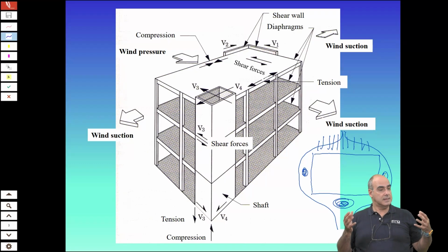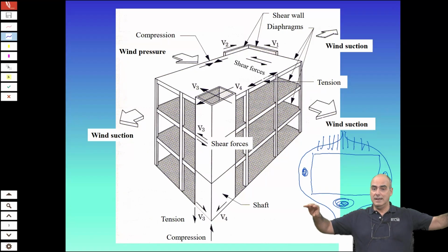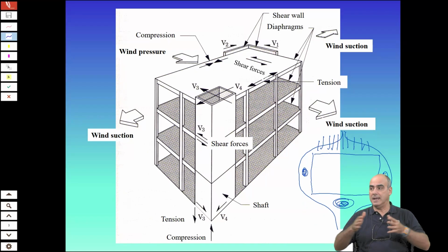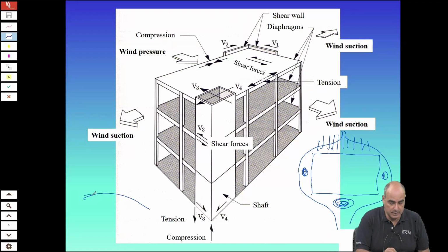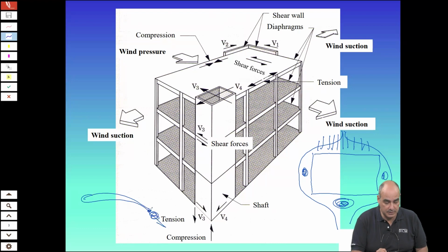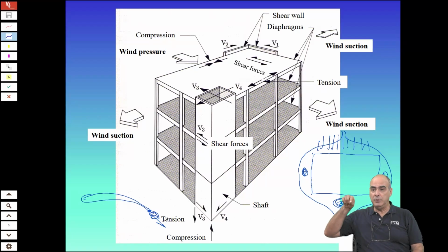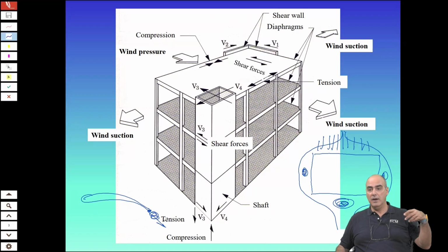Well, the same thing happens in airplanes. You have a wing. At the tip of the wing, you create a turbulence because there the airflow has a discontinuity. And also, the wing is shaped like this. Also here you create a turbulence. And as a matter of fact, the tip of the wings has some spikes, which are exactly to favor the detachment of the turbulence and bring it far away from the wing.